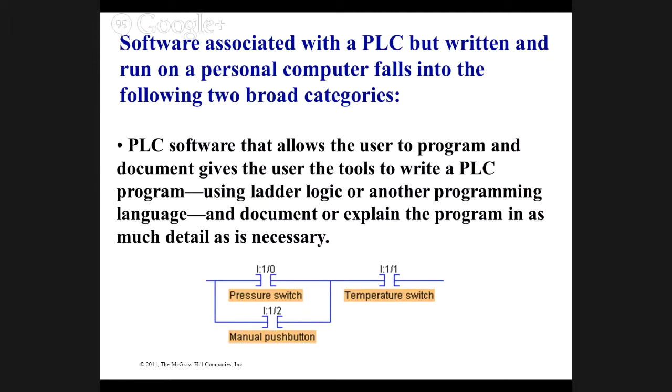So, PLC software that was written and run on a personal computer falls into two broad categories. First, software that allows the user to program and document, or to write the program, which is ladder logic. It also gives you the ability to document your program. So basically, the PLC program on your personal computer holds documentation to explain what's going on. The PLC program held inside the PLC does not. So you have to keep up with both.